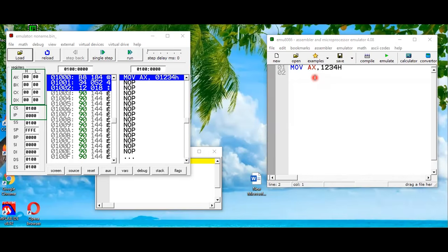And you know that every segment has to use two different pointers. One is known as the segment base address, which is the segment register, and the other is the offset address. And for the code segment, that is IP. So code segment will provide the segment base address. Let me write it for you so that this becomes easier.